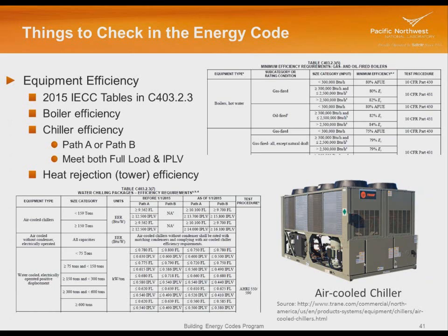We've got a control panel where all the controls are here to control the fans properly. There are control requirements on the fans. I'm not going to go into detail on that today. And then we actually may have the pumps for the chill water system built into the air-cooled chiller, or they may be separate. And we'll talk about hydronic requirements in a minute. So there's what your air-cooled chiller looks like. It's rated in EER. Again, the higher that number, the better.